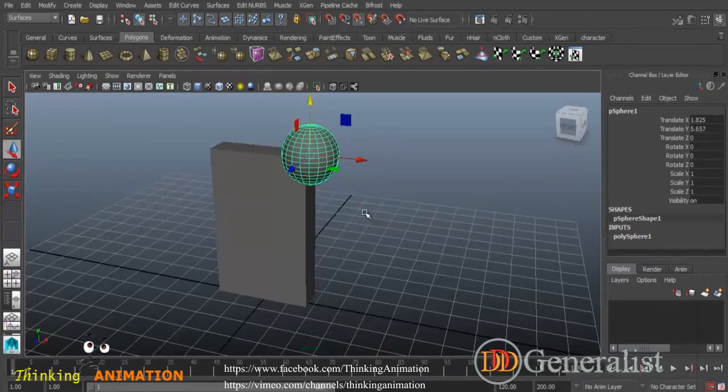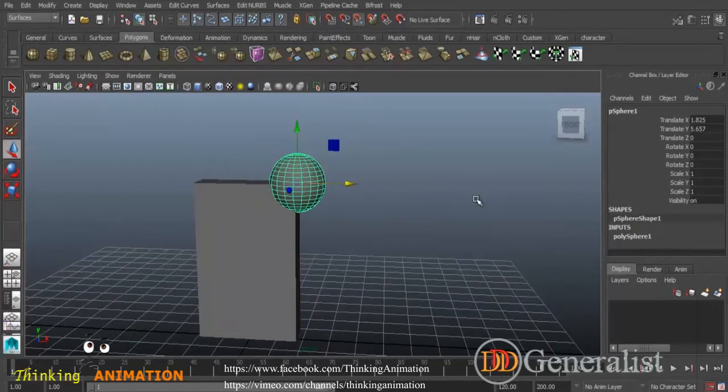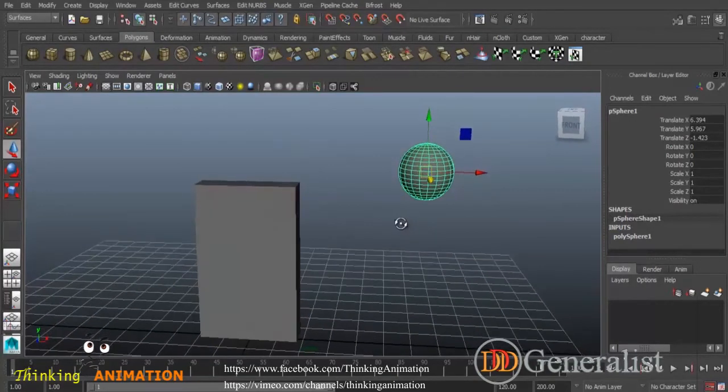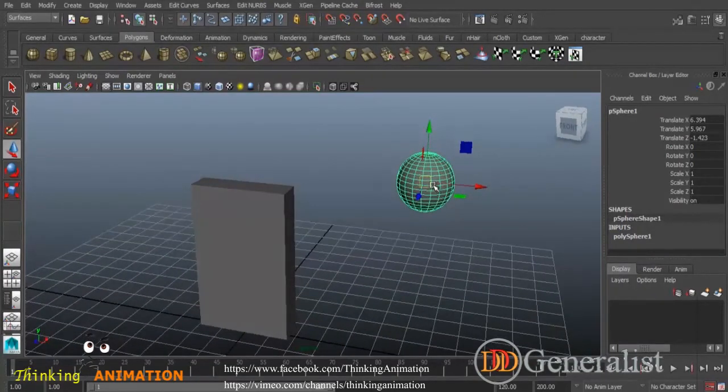And one important thing is to be noticed here. If I get him right here and deselect this one, if you move him along, snap to point is turned off now. Turn it off and then move him here. If you move him around in here and place him here. So if I want him to move on 3 axes, you select in the center of this object, and now you select this pivot point, this point, snap to point option turn on, and just pressing your middlemost button and moving your mouse around, it will snap from center to here.